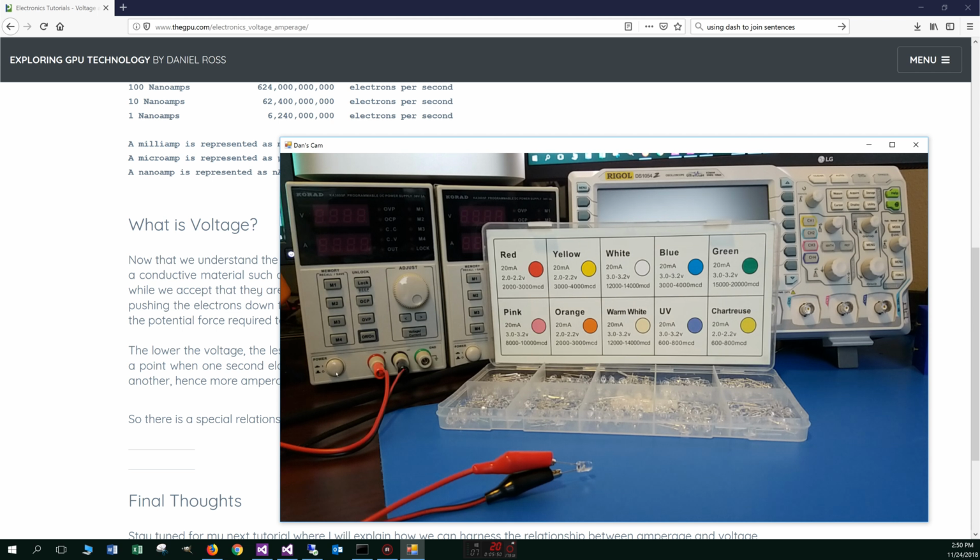It has a power button on it down here, and we'll go ahead and press that. Okay, it has a little on-off button right here, so nothing is happening. No current is getting sent to this until I actually press the on-off button right here. And I've got this dialed in, so volts up top here, 3 volts, and it will output a maximum current of 20 milliamps. Okay, so this is 1 amp. If it had a 1 over here with zeros, it'd be 100 milliamps. But this is the 10th slot, so this is 20 milliamps, which is 0.02 of an amp.